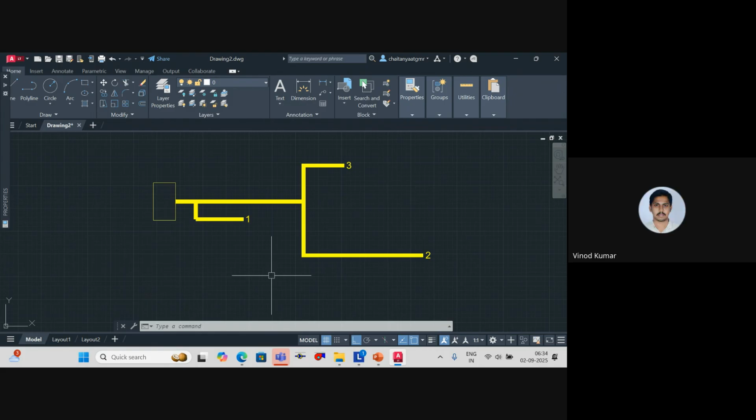Yeah, the reason is simple. As it's near, any fluid will flow in the least resistance path. You agree? That means wherever it is easier, or where I have lesser pressure losses in that particular area, I have more volume. And I'll get less volume in the location where I have more pressure losses. You agree? So the design stage itself will remove it.